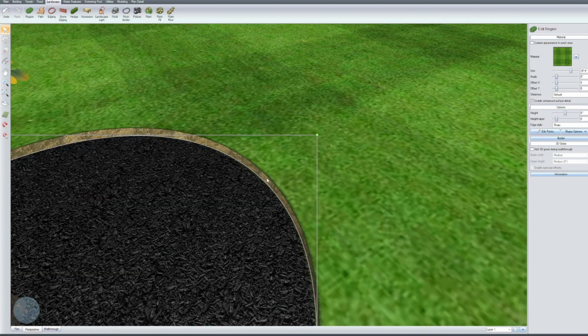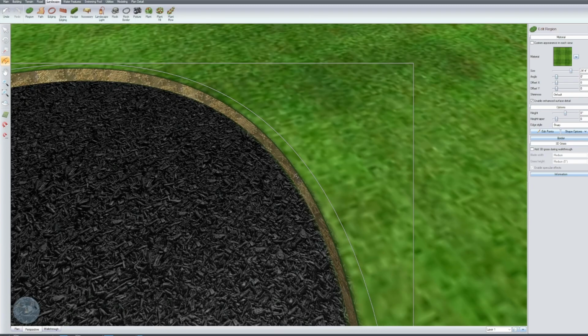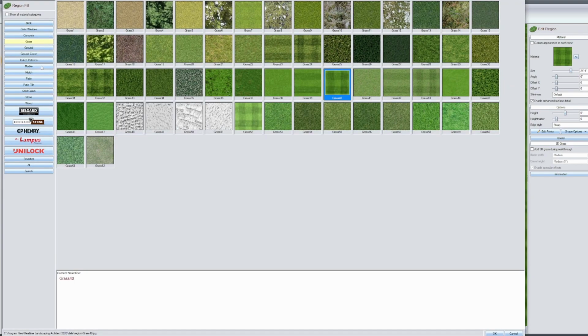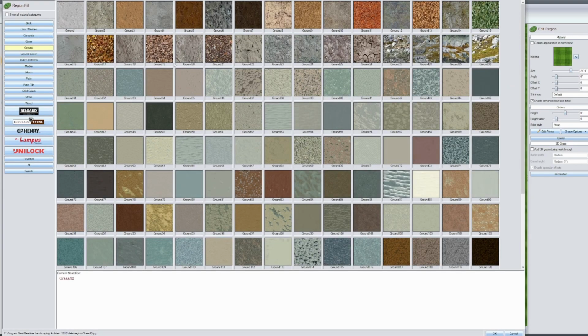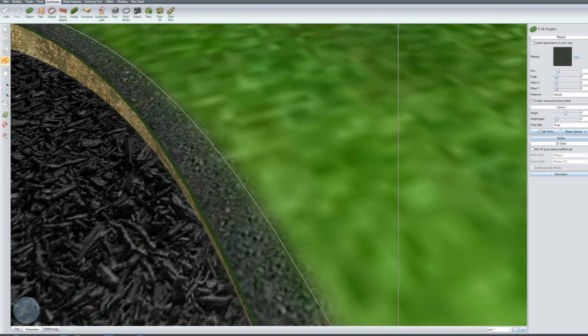Okay, the other thing, we are going to push our grass back so it doesn't spill into our bed. So right click, go to offset. And now let's just offset this. And you can see that it jumped up out of the bed, and now it's here on the terrain. Let's just offset it a little bit, something like that. Okay, if you wanted, you could give this an earth material. If we go back here, kind of like a topsoil, something like that, and you could see where that's sitting there.